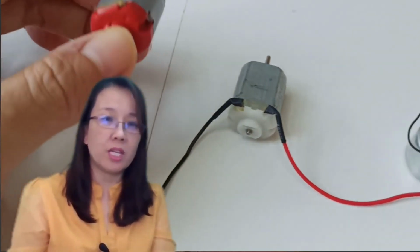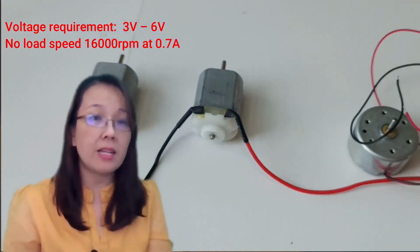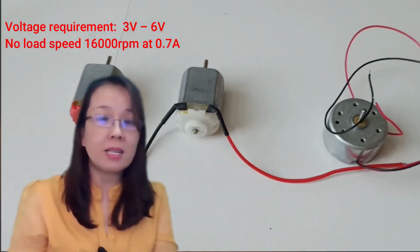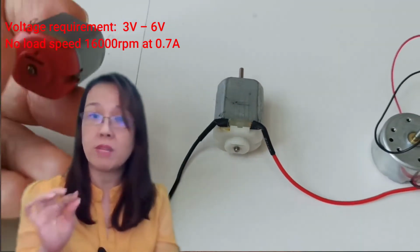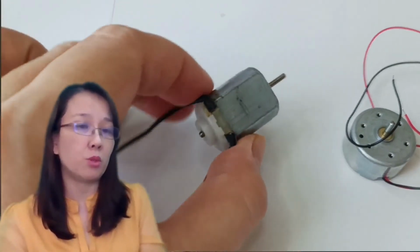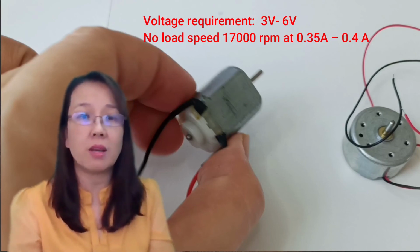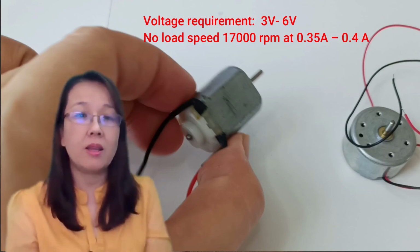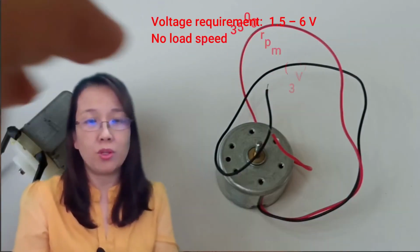Well, let us check on the first one. Okay, according to the specification, the voltage requirement is 3 volts to 6 volts, and it has a no load speed of 16,000 RPM, rotations per minute, at 0.7 ampere. 0.7 ampere is the current requirement. And this DC motor, the voltage requirement is 3 to 6 volts. That is 17,000 RPM at 0.35 ampere to 0.4 ampere. That's the current. And this particular motor seems to be the lowest.